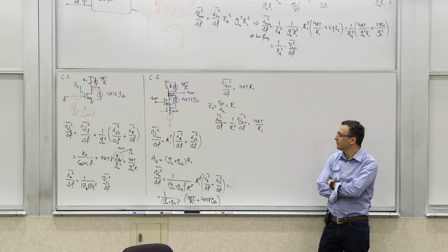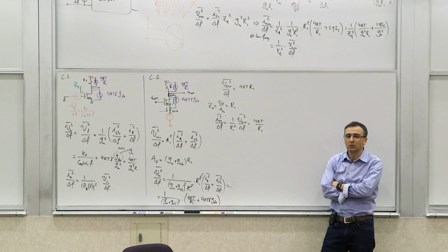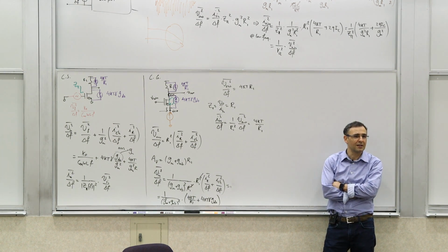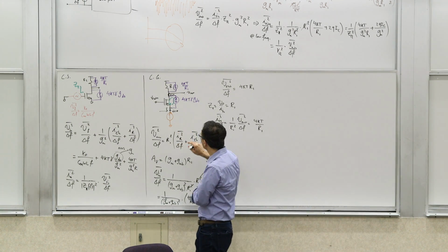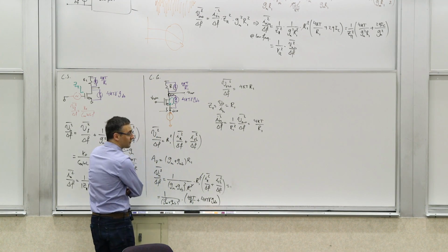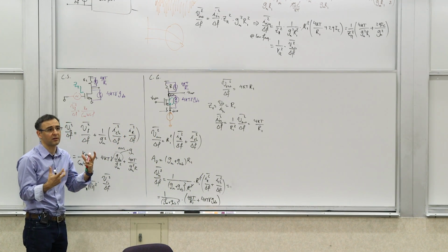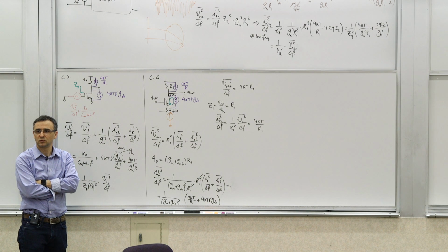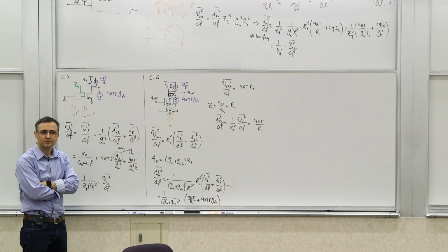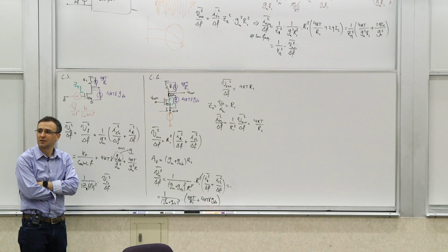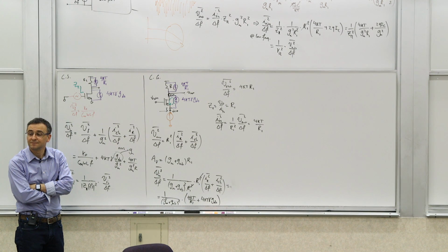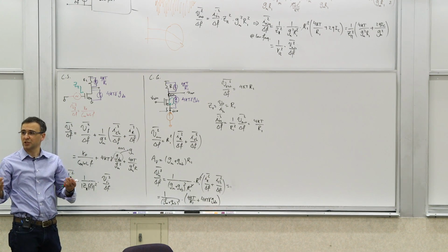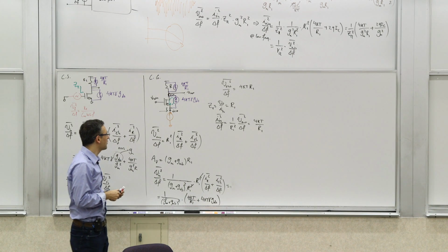The other observation I have for you is: are these noise sources fully correlated, uncorrelated? What can you say about the correlation between the input referred current source and the input referred voltage source, the two that we need to characterize any two-port noise system? Yes? Correlated but not 100% correlated? Say again? Are they correlated but not 100%? Well, so they're partially correlated, correct, exactly. They're not 100% correlated. Why?